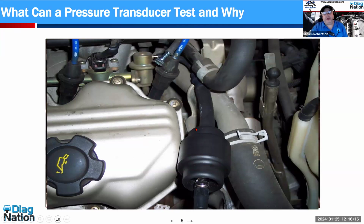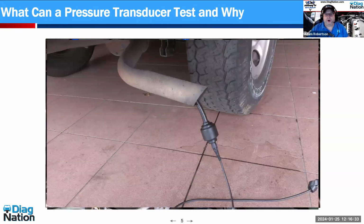But continuing on with this, in this case I'm using a Delta pressure transducer and measuring, once again, the pulses inside the fuel pressure regulator right here. Just a different engine, a little different hookup, but I've gone from an absolute pressure sensor to Delta, and that was a great time for that question. Let's move on. Here, I've now installed a Delta pressure transducer in the exhaust, once again measuring those pulses.